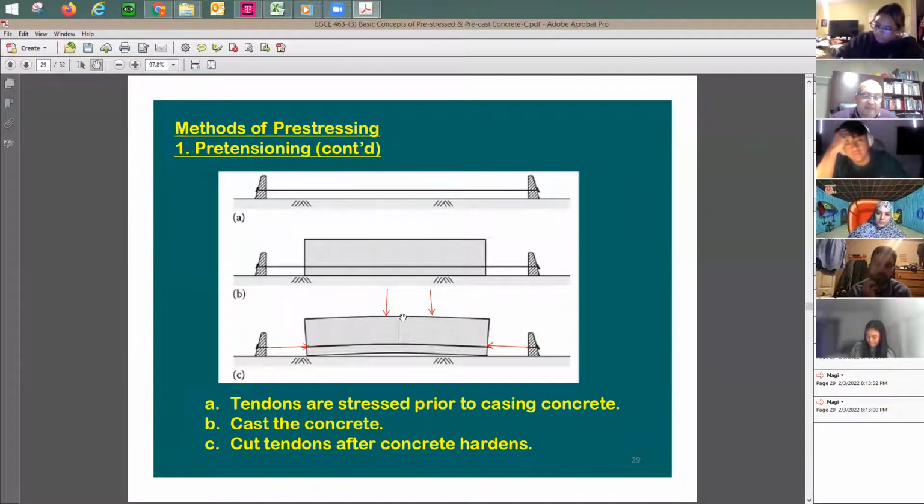Now this means I have a very low amount of strain on the top, and I may also have some tensile strain on the top in the concrete. So instead of putting only, let's say, 1 kip, now I'm going to be able to put 1 1/4 kips. Now I have more capacity here to add loads with this pre-stressing at the bottom of the beam.